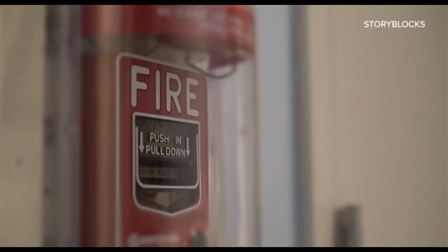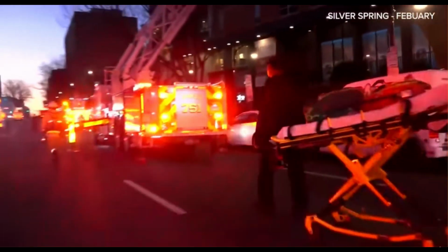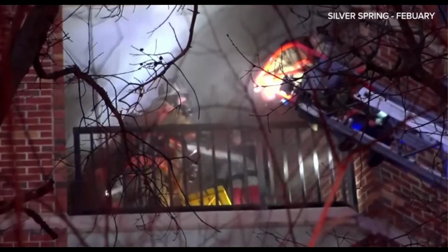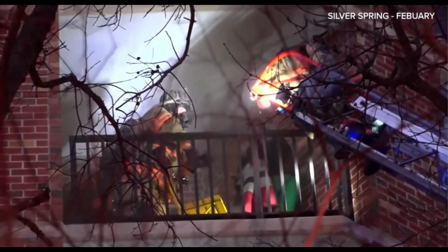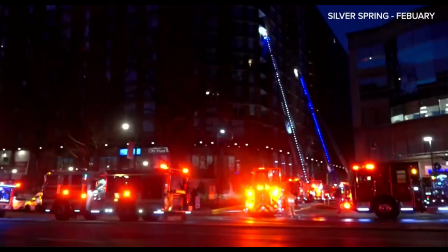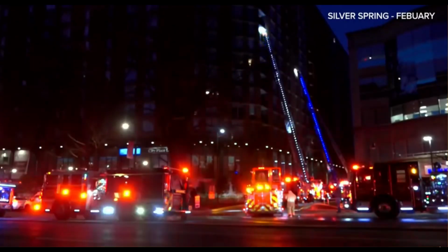The goal of the fire alarm is to get people out of harm's way, and the people most at risk are those near the fire. Limiting alarms to the 3 highest risk floors means stairways are as clear as possible. That lets people near the fire evacuate faster rather than getting stuck in a crowded staircase.